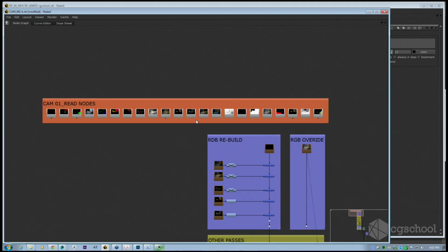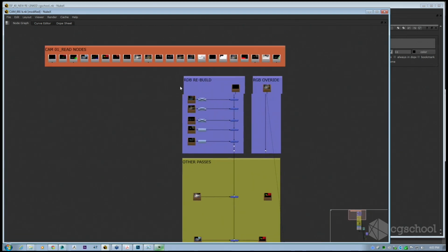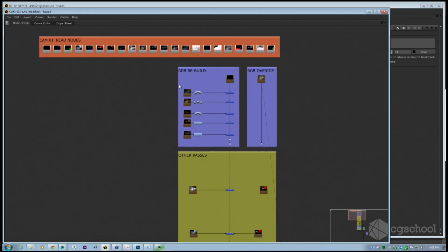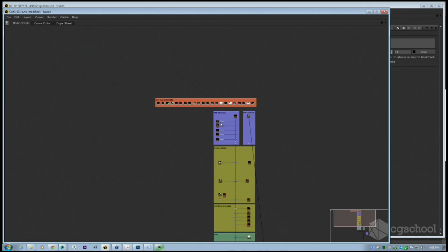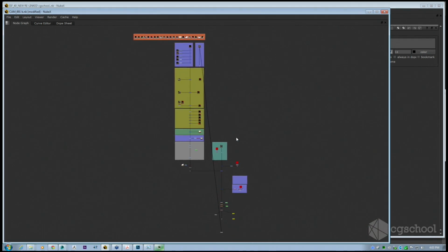And then whenever you update the camera, the lighting, any of the models, you can just press restart on that job in Backburner, and it's going to update everything for you, and render everything out in the same current folder, and all these nodes are going to update automatically. So that gives us this mega fast workflow of essentially rendering out a set of images and setting up a comp like this. Now we've got the comp set up, we don't have to do that again.